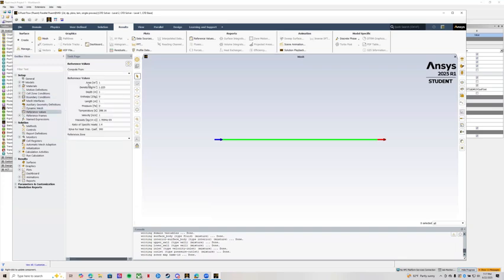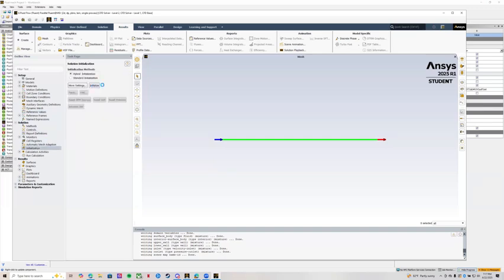We're going to our reference values again. We're going to select it, go from our inlet, and you can notice all the values get corrected to surface body. Now we can go down and initialize the hybrid again. We're going to let that run. This is where we're going to get an error message, just because we don't reach down to that level of accuracy. That's okay.